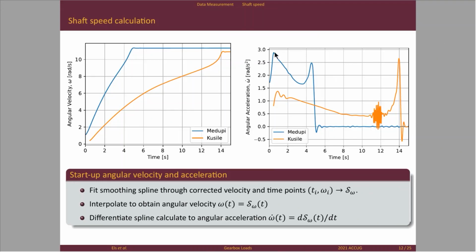You will see that for the direct start, there's a very large acceleration of the whole system as it starts up. The thyristor soft start in the end also gives you a value that is comparable to the normal direct start. So you will see that effect in the torque as well.